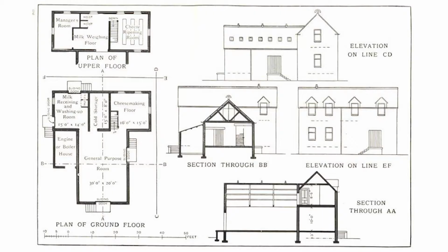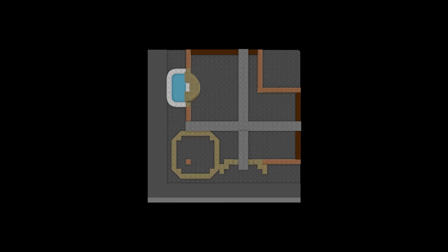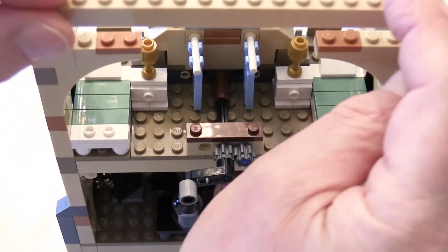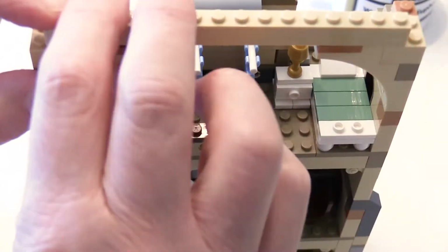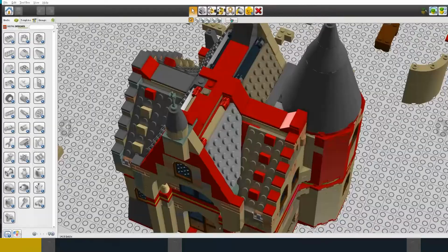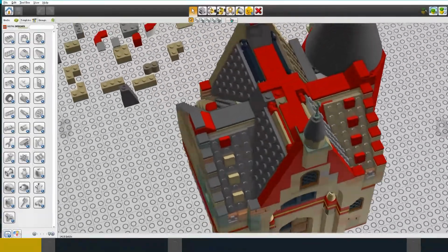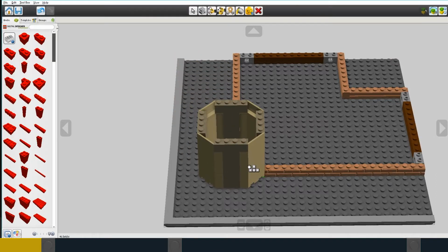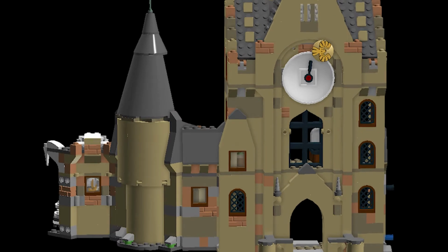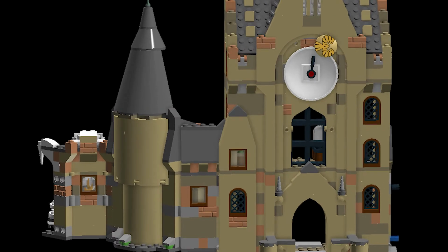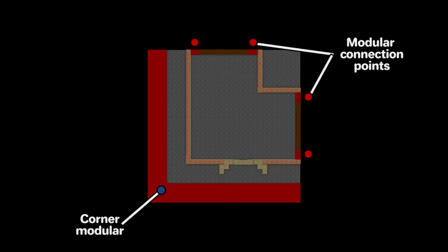and outlines leading to what would be called in architectural terms the elevations of the building on the different sides, locations of doorways and entrances, wall thicknesses and openings or gaps in the walls, how the floors and roof will be supported, the design of the roof, that's the shape and how it will be constructed, and for this mock, the design of the tower, that's its size and shape and how to make it, the location of the main features like the arch at the front and the clock and the fountain at the side, and how it will meet the modular standards like the positioning of modular connection points, blank or connecting walls, and the pavement, etc.